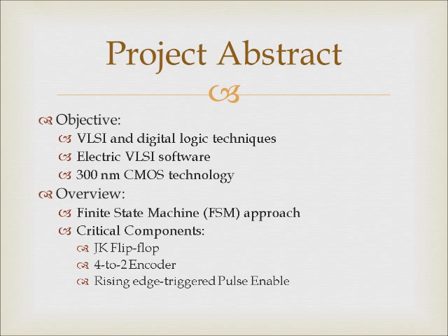flags. Some critical components include JK flip-flops, which serve as memory for the finite state machine, a 4-to-2 encoder to convert input signals into binary, and a rising edge triggered pulse generator to serve as a clock and for debouncing purposes.